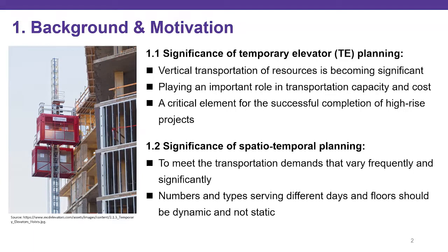The transportation demand for temporary elevators varies frequently and significantly. To that effect, temporary elevator planning should be adjusted accordingly to meet actual transportation demands. In other words, the number and the type of temporary elevators serving different days and floors should be dynamic and not static.